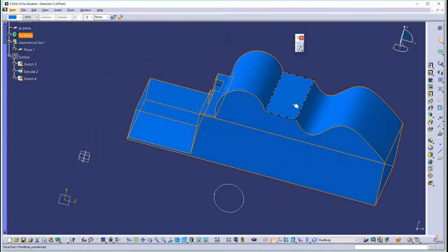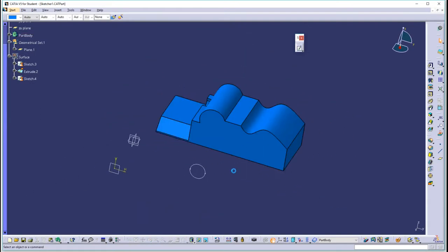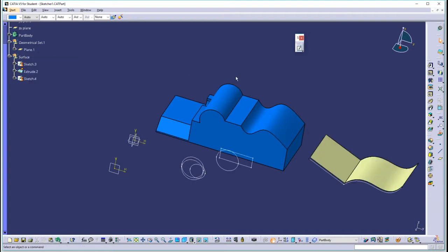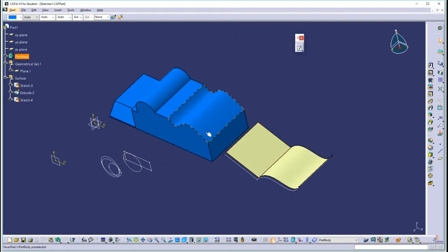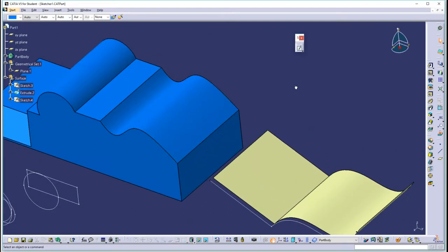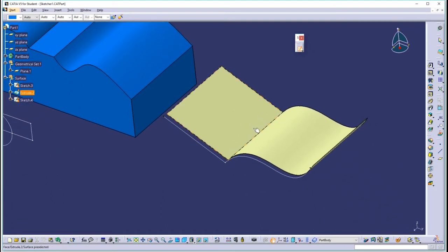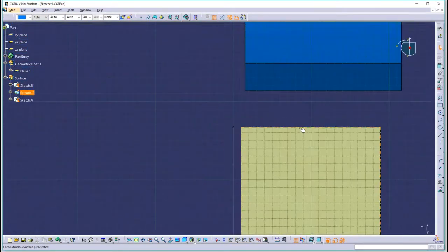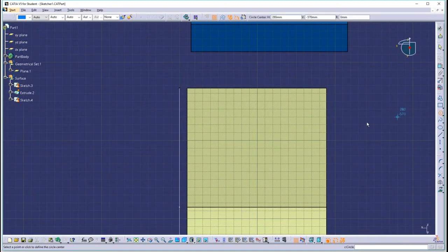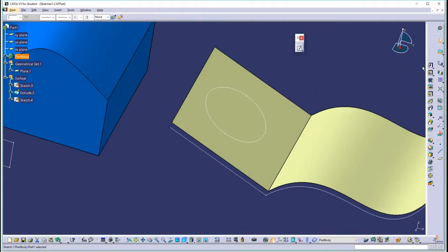Now let's take a look at whether we can sketch on things that are not solid and not planes. I've already created a few things in this model for you. I've created some surfaces. We haven't learned how to do surfaces yet, but eventually you will. Let's select the Sketcher icon and let's sketch on. Again, as you hover your mouse over a surface that's curved, it doesn't highlight. Only flat surfaces highlight. You can select a flat surface and we can draw on there.